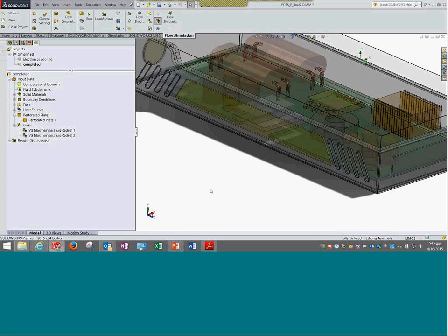As we may not expect the flow to be happening only from those holes. So these are not actual, but these are imaginary holes. We are using this option only to create a kind of resistance which a perforated plate can bring into the system. Both resistance as well as the amount of air that is permitted to come in through this particular perforated plate.